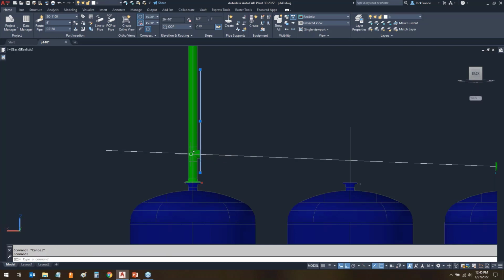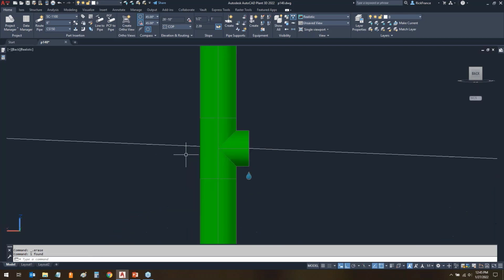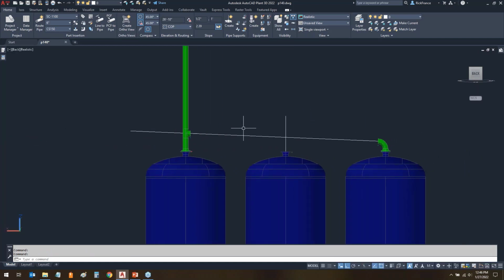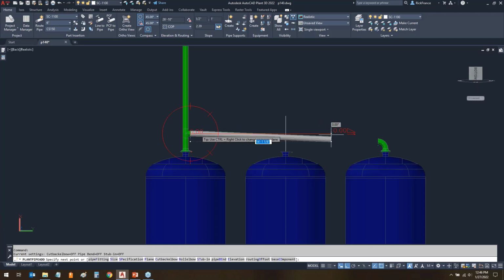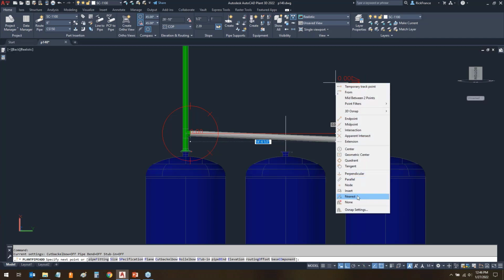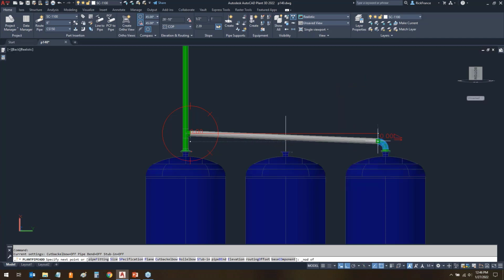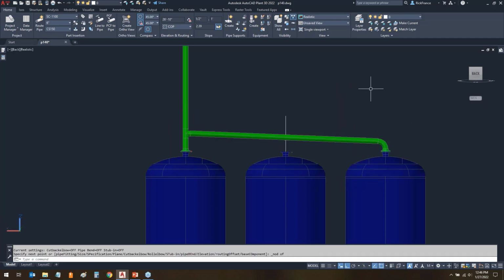The outlet, you can see here, if I zoom in, it's not on that right there. It's crossing through there. So that's why I use the outlet. Once I've got that in there though, it's ready to connect up. I'll just shift right click for the node. And there you go. I got my slope pipe on the header correct.